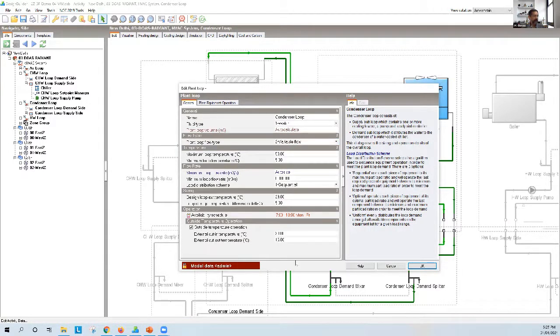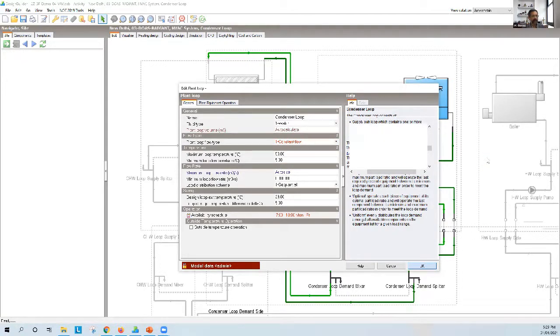You can decide to follow the chiller's operation with outside temperature if you wanted to. That's something you can do. In most condenser water loops, engineers don't like to see a variable flow because the chiller needs to get cooling. If you don't provide the chiller the right amount of cooling, you may cause the chiller to go to fault, and that's a much more dangerous thing to do than just saving a few kilowatt hours on variable flow. But that's something, again, you can talk to your mechanical engineer.